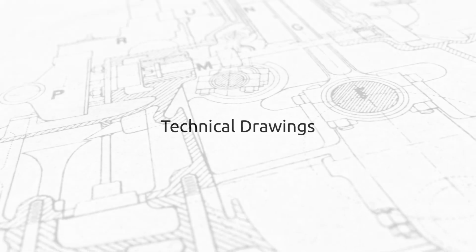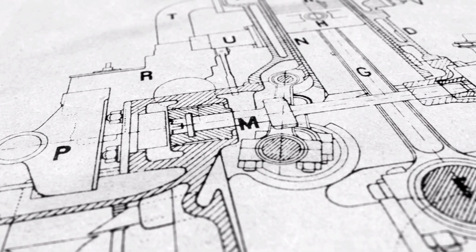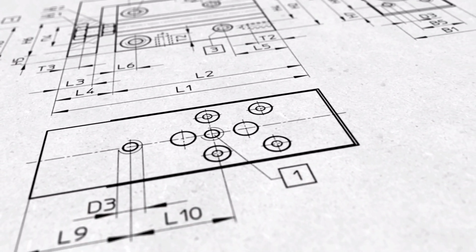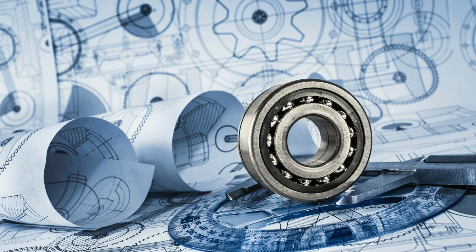But for now, let us wrap up the files that you need for manufacturing hard goods with technical drawings. The technical drawings are a complement to the 3D models that your mechanical engineer is now creating, and they show you things about your product such as surface coating, tolerances, and way of assembly. You will need these because most manufacturers won't even quote you unless you can provide these technical drawings as a complement to your 3D models.